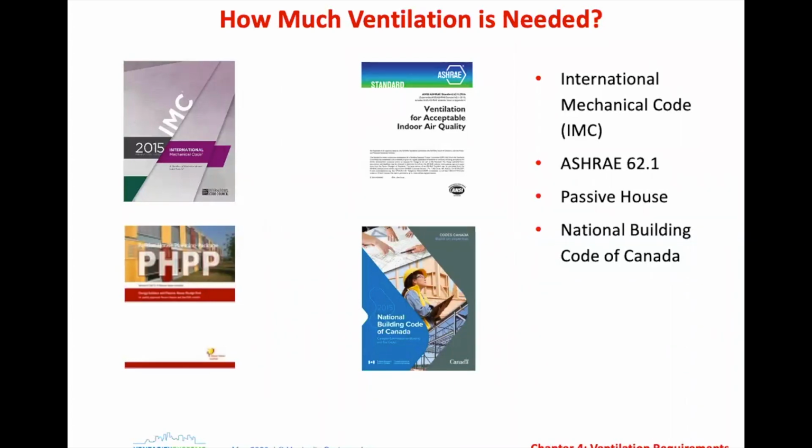That has to do with the design flows, which are what we're primarily talking about today. But that also covers things like fire dampers and other metrics of the International Mechanical Code for duct sizing, and again, fire dampers, smoke dampers, that type of thing. Always check with your local jurisdiction. So all of these standards will have requirements for ventilation.